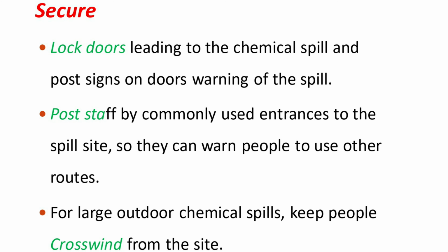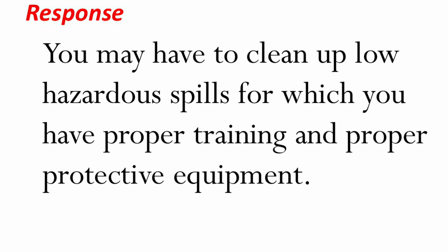Secure. Lock doors leading to the chemical spill, and post signs on doors warning of the spill. Post staff by commonly used entrances to the spill site, so they can warn people to use other routes. For large outdoor chemical spills, keep people crosswind from the site. Response: you may have to clean up low hazardous spills for which you have proper training and proper protective equipment.